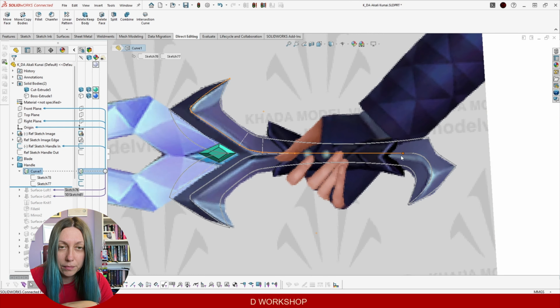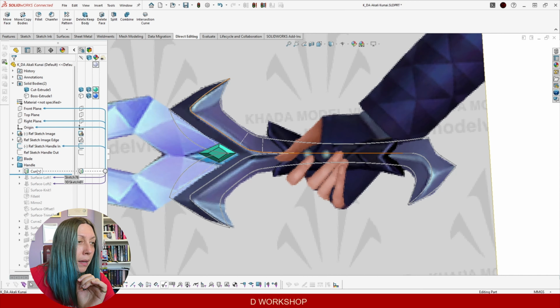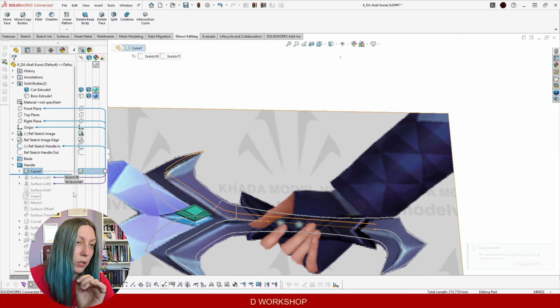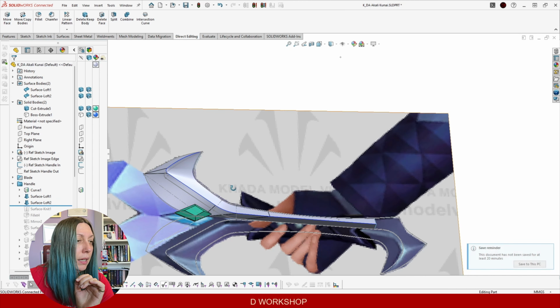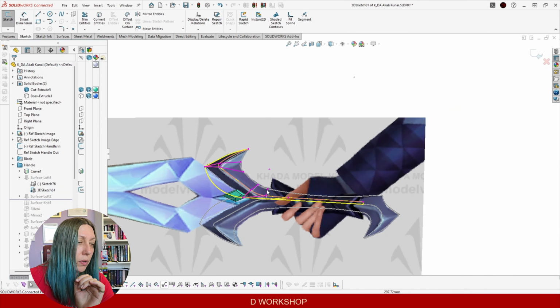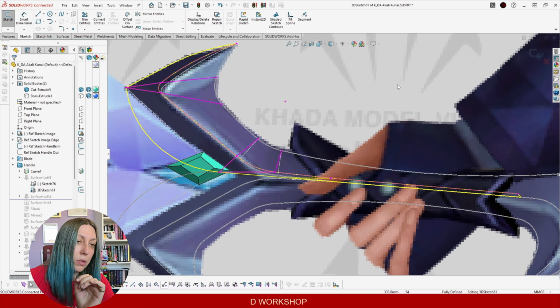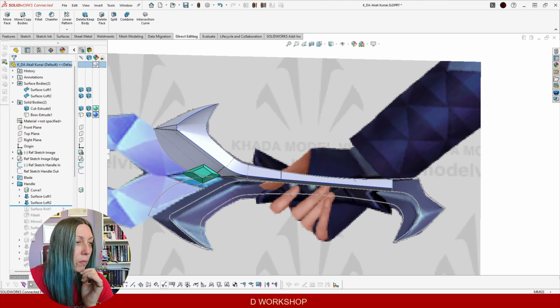on the top of the handle, and I stop up to here. Up to here we have it symmetrical, so I will stop up to here and I will build the rest later. Now I will make just this half, mirror it, and continue with the rest. I start with curve, which is sketch projected on sketch, and then I start with the surface loft, outer edge to the curve, and then inner edge to the curve. For the outer, I even did some 3D sketch which I use as guiding curves. So I have it nice and exactly as I wanted.